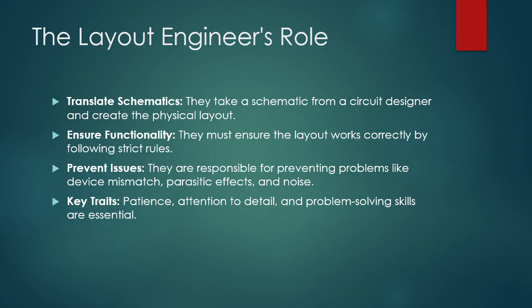As I told earlier, a layout engineer's role is to translate the given schematic circuit, which is given by a circuit design engineer, that may be a digital circuit or an analog circuit, into the physical layout using transistors, resistors, etc. We must ensure that the layout we have done matches the given schematic.